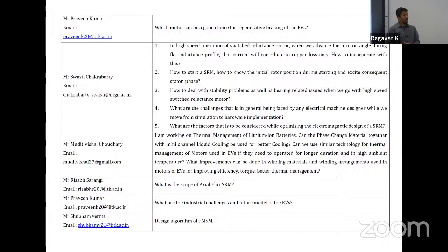But in a real setup, you would either have a position encoder that gives you the feedback and maintains it using an absolute encoder, or you would end up creating an offline observer that maintains the position. Like you saw what I had done for one of the methods I showed you, that actually was for standstill. If you have a specific inductance profile, you can use inductance directly to calculate the initial position. So for initial position sensorless, there are several methods, but if you want to do it in a way that is very reliable, oftentimes people just toss in hard alignment.